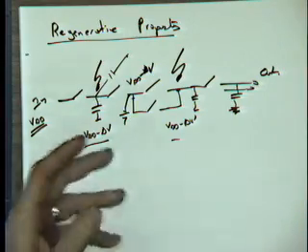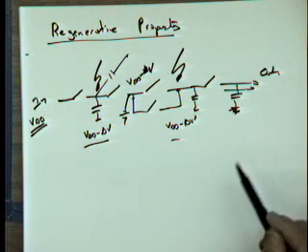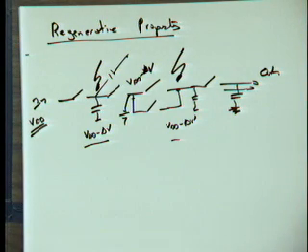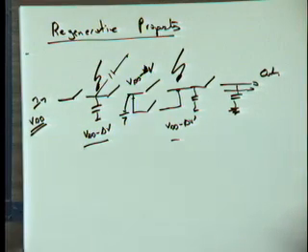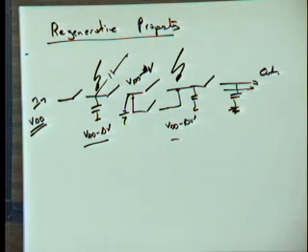Noise comes in and it accumulates. And the deeper you go, the more noise, and suddenly you might not be able to figure out if it's a 1 or a 0 anymore. So that's an example of a non-regenerative network. It's clearly something that's not scalable. You cannot make very complex networks that way. So that's why we would like to see our digital gates have this regenerative property.